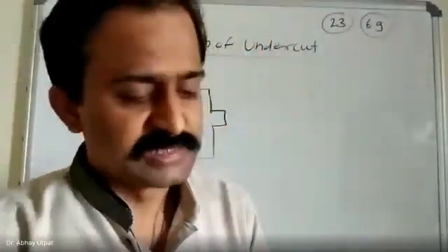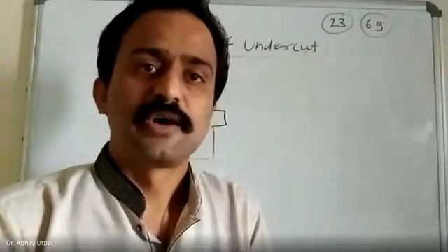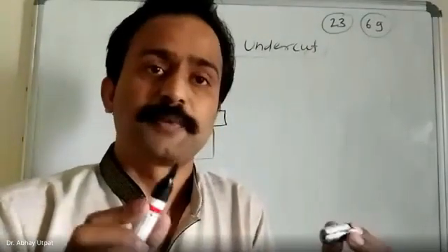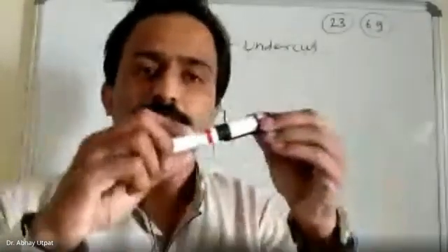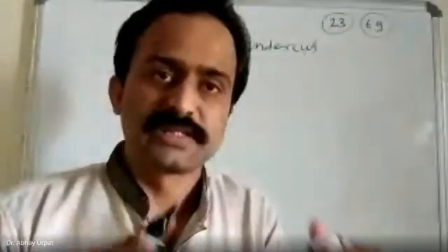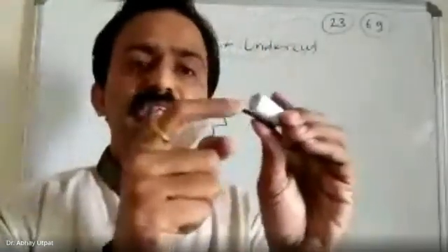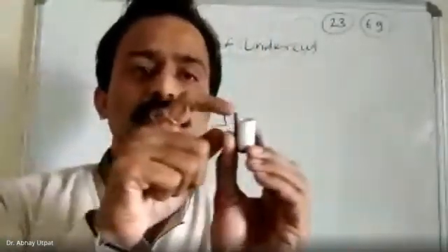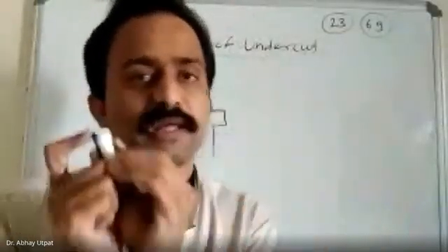Actually, the inside ring is of a little smaller dimension than this hole and shaft. This concept you have studied in that AMQC subject. So here it is not fitting well, but when I am pressing it, it is an interference fit. So this part is strippable. See, you can look at this. I can easily strip it for removal purpose.